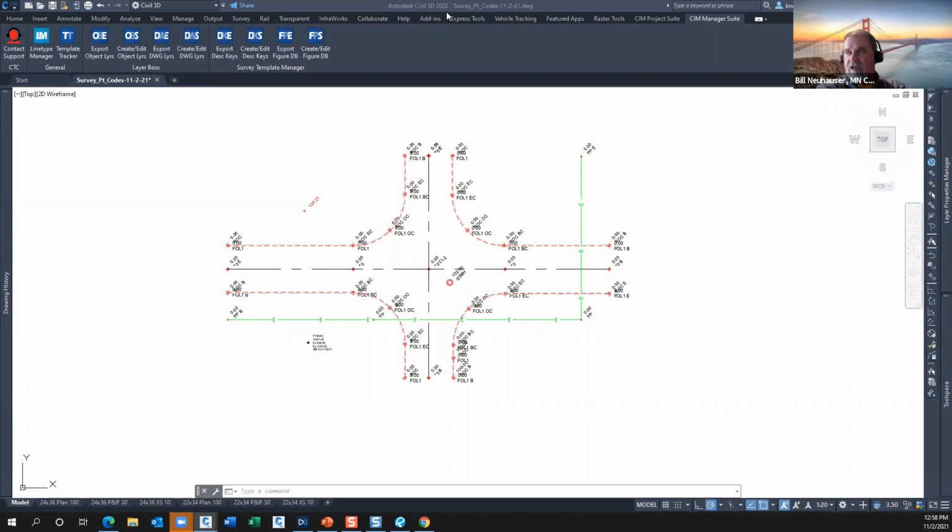So even though it might look pretty, it might be beneficial for your crew, if they shoot multiple shots, to designate only one of them as being on curve, maybe out at the midpoint, just to make things look pretty. And the key in that one is to make sure you don't use that as a break line, because if you do, it's going to skip all those other intermediate shots, which is going to mess things up. So, nothing's perfect, right?